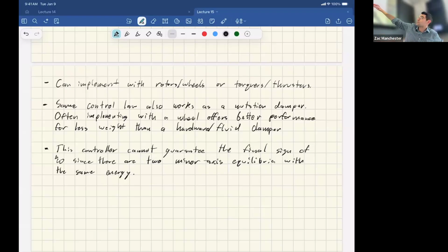So again, this is a nice, convenient, simple way to get, if I give you a torque that I want, and you have an array with more actuators than degrees of freedom, roughly speaking, an evenly distributed solution. It'll evenly distribute the torque of the momentum over the array and overall minimize the individual wheel speeds.